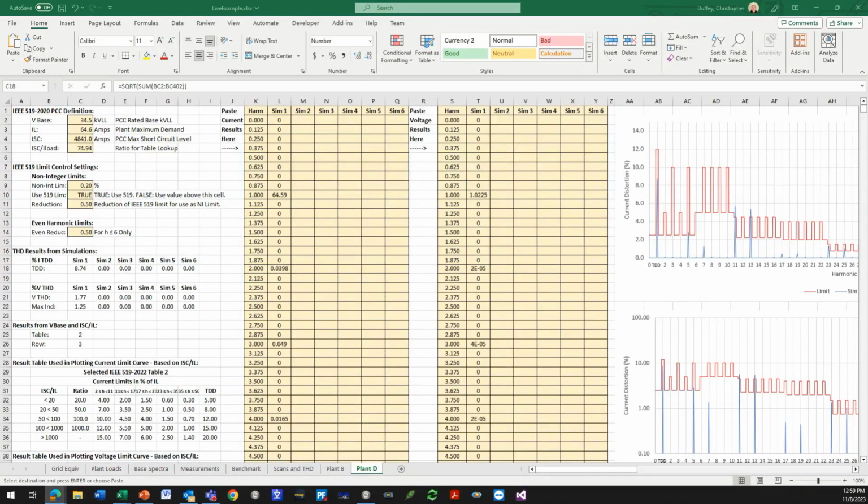And then on top of that, the magnetizing current is very, very small. It's around 1% of the rating. And the third harmonic that's within the magnetizing current is even smaller than that. So it's going to be no more than, gee, I don't know, 15%, maybe 20% of your magnetizing current magnitude. So that's a very, very small amount of current, and I would think it has very small impact. But like I said, when you have a resonance in the wrong place, even small levels of current can be amplified. And so you might have to consider that, yes.